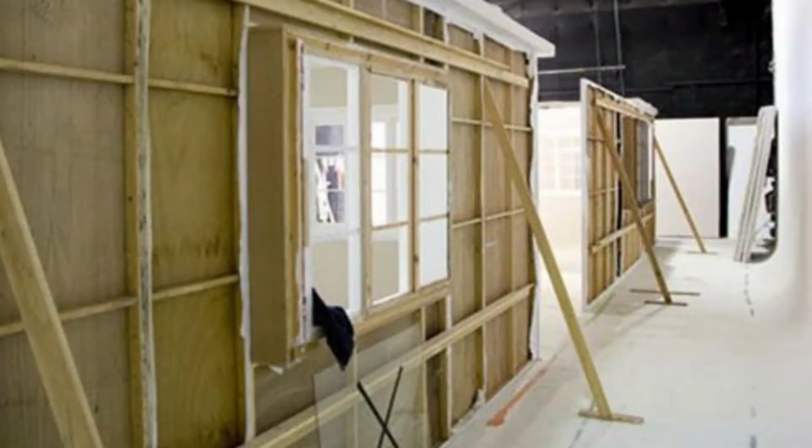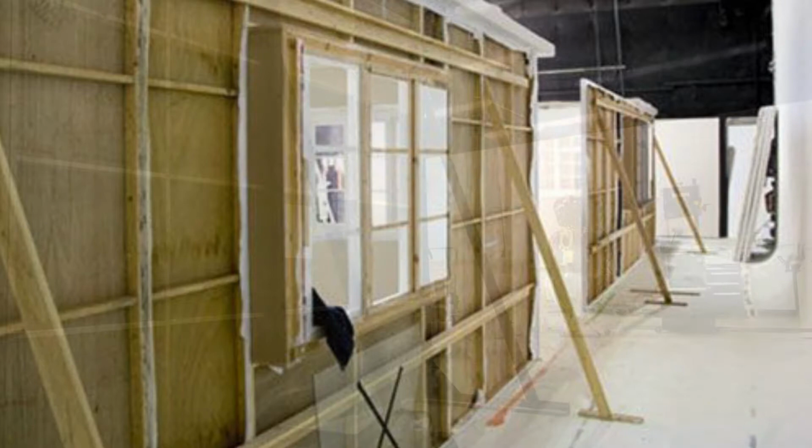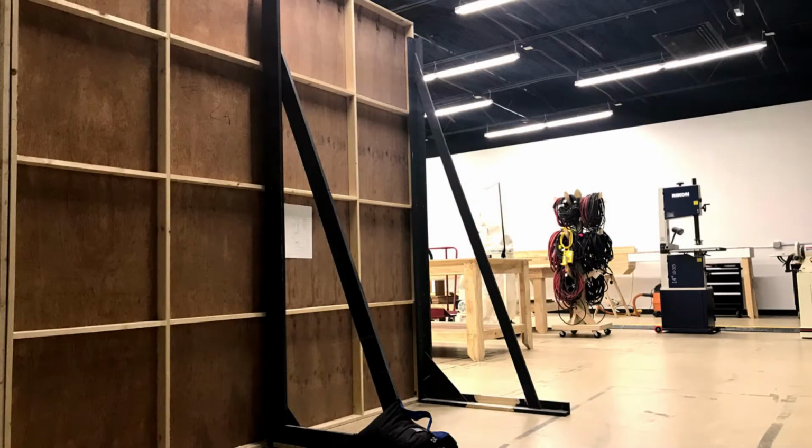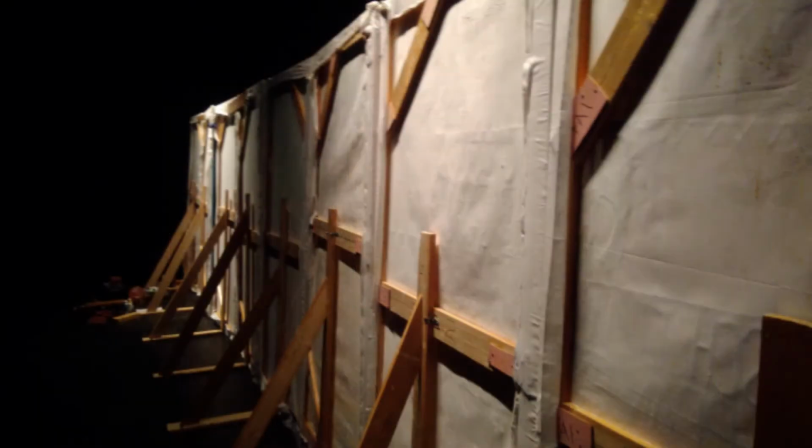The scenic design must be broken down into buildable elements, taking into account any constraints of the venue or planned transportation. Of course, there's no one right way to do the job, but there are construction standards well known to all stagehands. Flats and platforms are the most basic building blocks for creating a set, and most scenic carpenters learn to construct these elements first. Flats are frequently used to build walls, architectural elements, and offstage masking. They can be framed in wood or metal, covered in a hard material or a soft fabric, and built to any size manageable by hand.